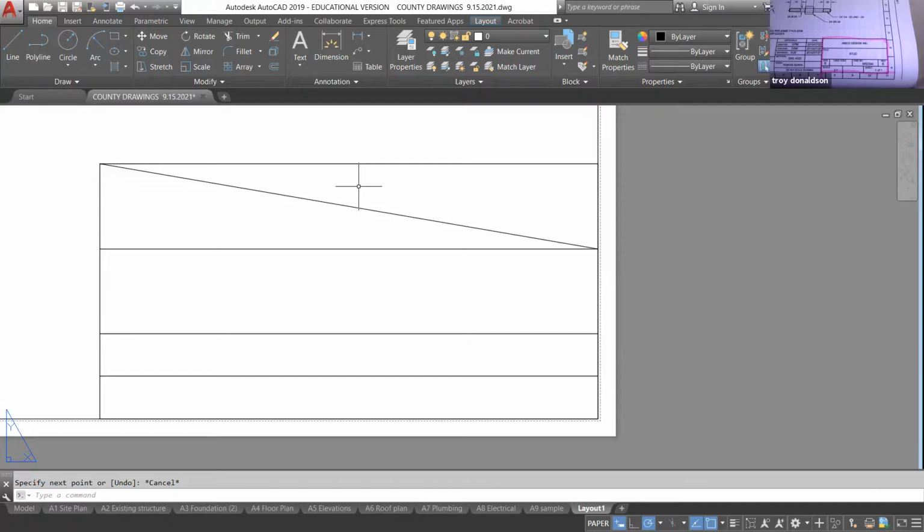Okay. So now I'm going to do a single line of text. And it says specify the start point. So I'm just going to go ahead and choose that as my start point. Okay. And then it says specify the angle. I'm just going to hit enter to accept 0 because I do want it horizontal. Then I'm going to try and just type. We'll see what happens. A, N, C, O. And you get to put in whatever name you want, right? So with single line text, you have to enter twice and it places it.